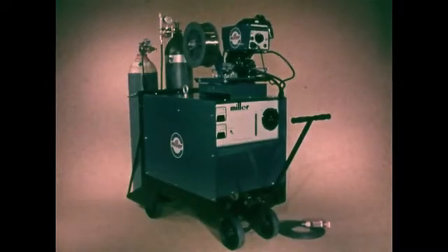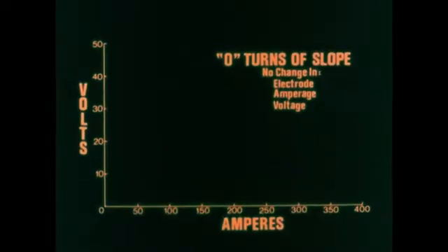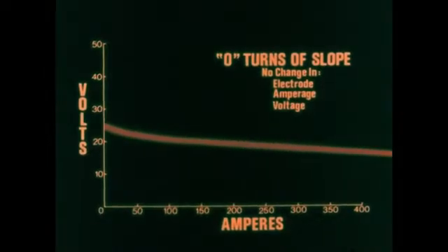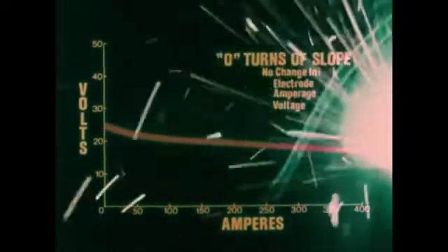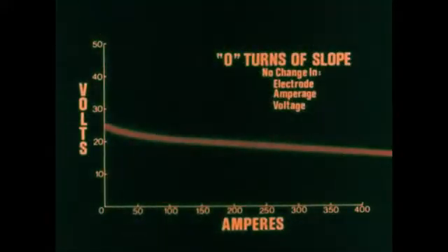Power sources, such as the 250 ampere constant potential or constant voltage machine in use here, offer the opportunity to control the amount of maximum short-circuit current and its rate of response. This graph illustrates that if there were no control over the current, it would simply surge to a very high amperage, far beyond the design parameters of the power source, until the wire electrode literally exploded.